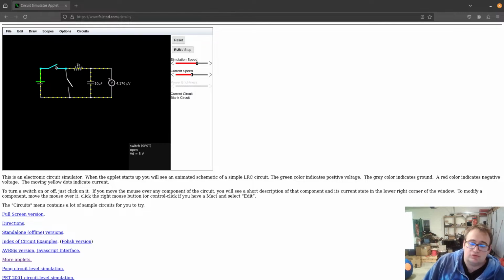But now we'll close this, and when I close it, the current from the battery will flow through the resistor into the capacitor. And eventually the capacitor will get fully charged and will just be held right at that 5 volts. See? Charge, charge, charge. And now I'll open, close. You see now we discharge it through there. Now, a question you might ask